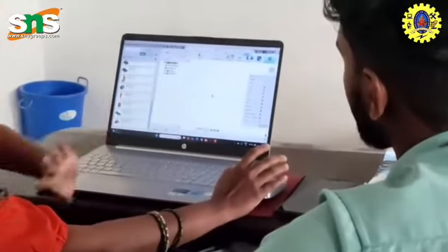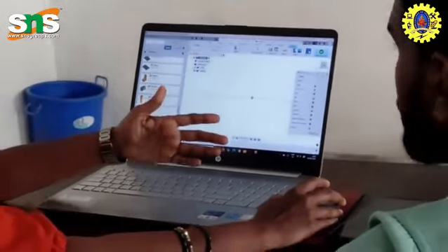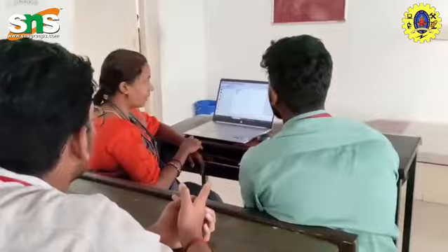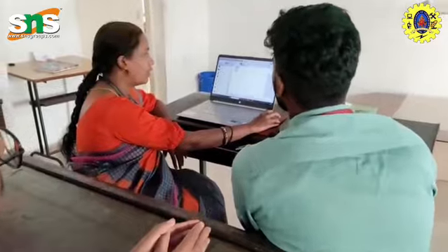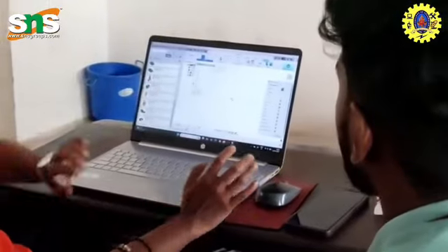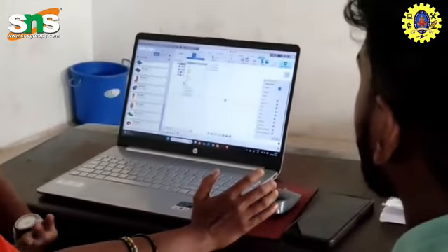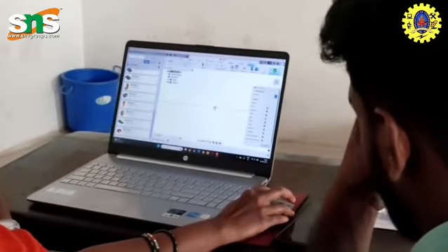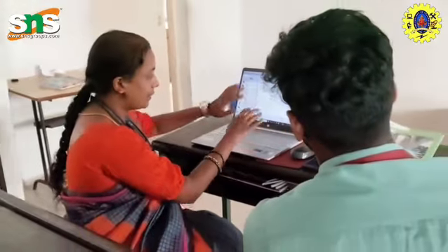The views are in 2D. If I want to convert this into a solid, which option could I select? Say for example, I am drawing a rectangle. I have three options: a 2-point rectangle, a 3-point rectangle and a center rectangle. If I select the center rectangle, I have to keep the cursor here and simply draw a rectangle.